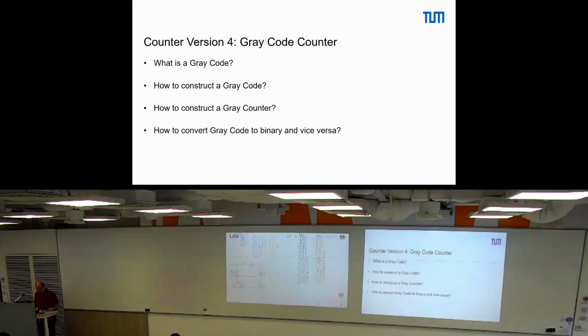That was binary to gray. For gray to binary, effectively in the upper half, if we have here a 0 and here a 0, then we have the same. So if these two bits are the same, then we have 0011. If here and here are the same, so both 1, then here we also have 0011. So if they are the same, that is actually the outcome of this bit. So we feed this into another XOR, have here B1, and the second input is G1.